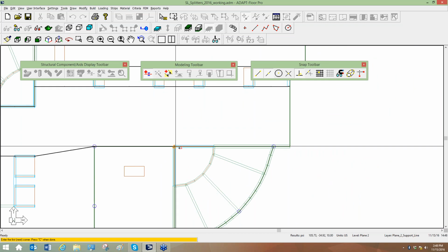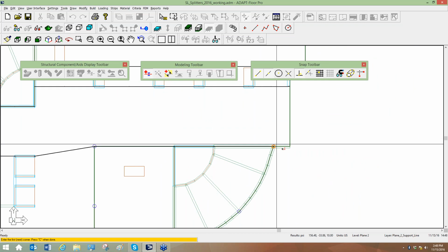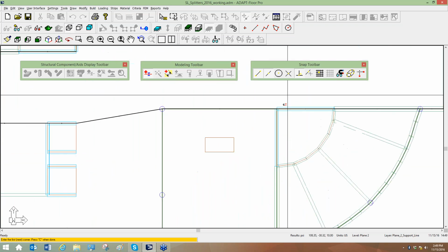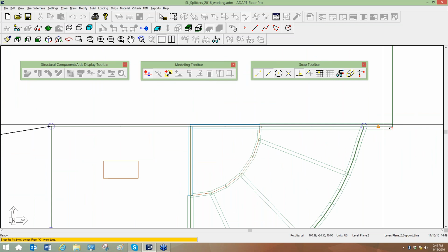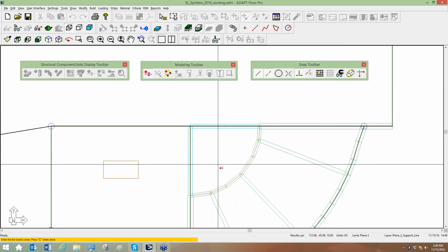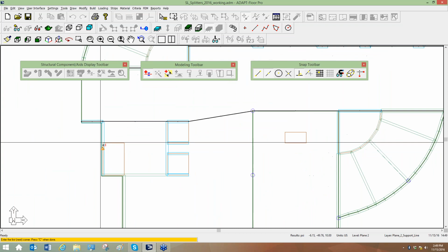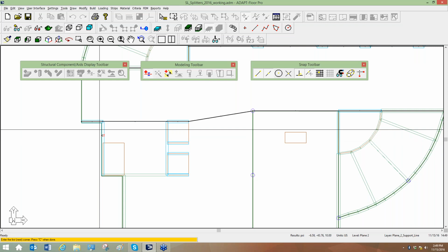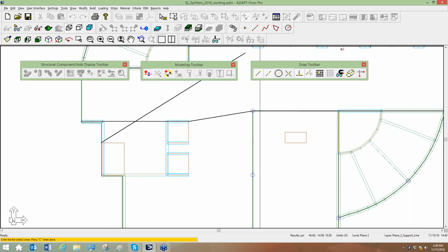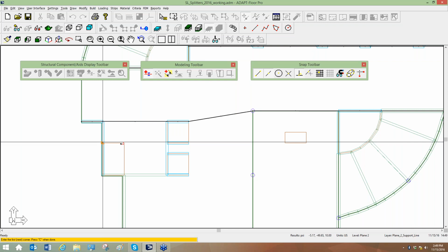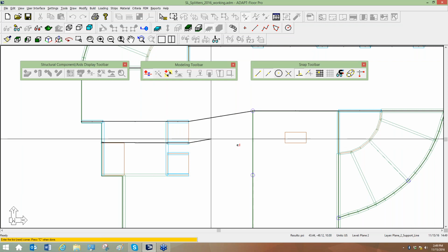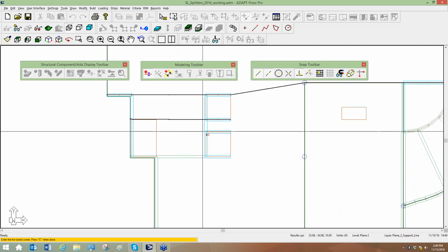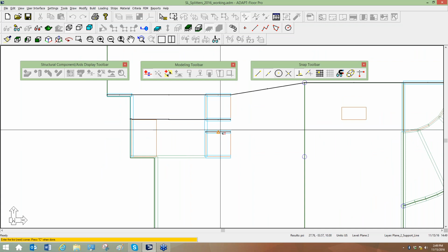And remember, here I'm just really snapping on the walls, ends of walls and columns. There's also some beams along the path. You can see there's a beam here. And I'll talk about beams in a moment, if time permits. I'll turn on my snap to nearest, and now I can snap anywhere along that slab edge. I'll just snap there, and we'll go snap middle of wall, and then I'll stop. I'm also going to just put a small support line over this wall.